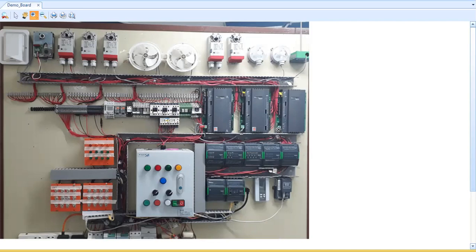So it is bus technology or bus protocol, using RS485 cable. The network protocol is bus, and the communication protocol is BACnet MSTP. So from one DDC BACnet controller, it communicates through this BACnet MSTP network connected to my automation server. So that is the answer to your first question.